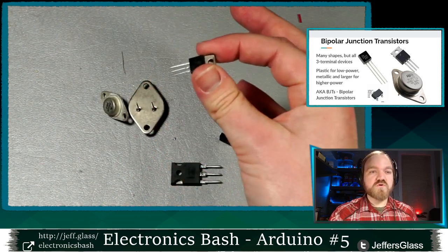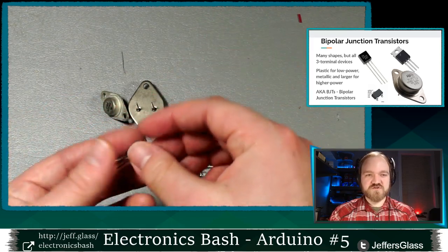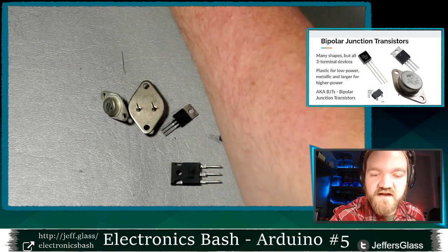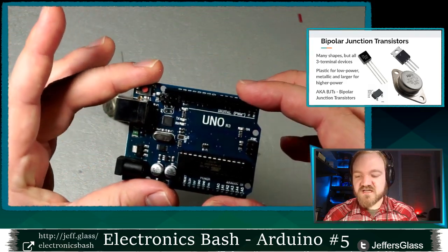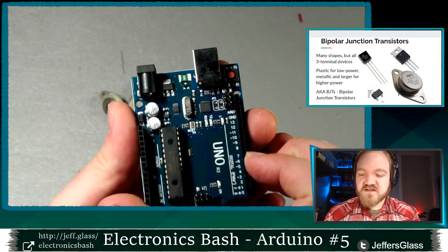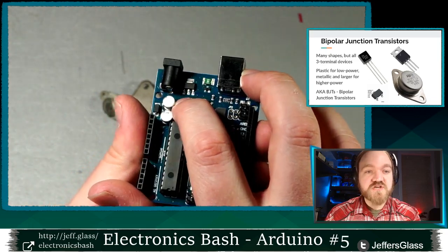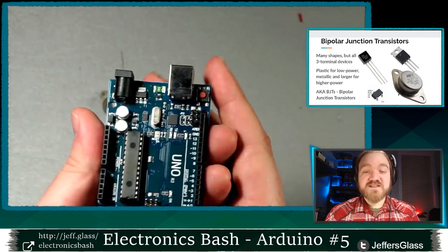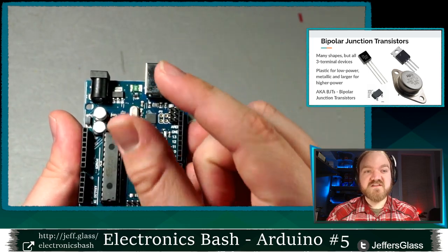These are all through-hole components. You're meant to solder them onto a circuit board or stick them in a breadboard. They go down in size also to things like a surface mount device, like you might see on your Arduino Uno, where there are actually no holes through the circuit board. The device is just soldered onto the top. There are transistors in that form factor too, and in fact they get very, very small.